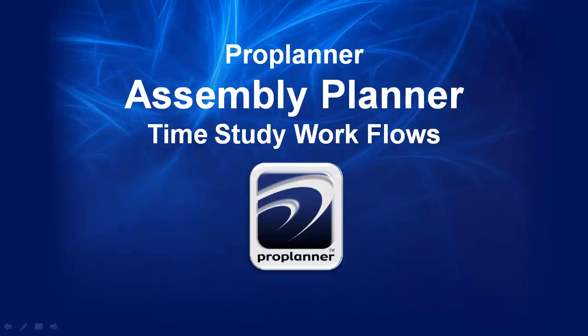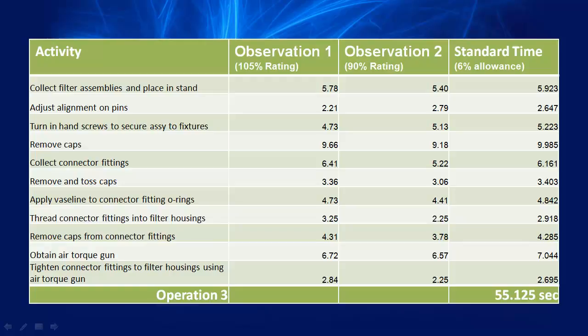Activities represent work tasks, so I'm going to use the word activity and task interchangeably. Typically, when an observed time study is performed, multiple tasks are observed and timed. For now, let's say we're performing a time study on all of the work in one station. This work would include many tasks. By summing the time of each observed task, we can get the total work content for the station.